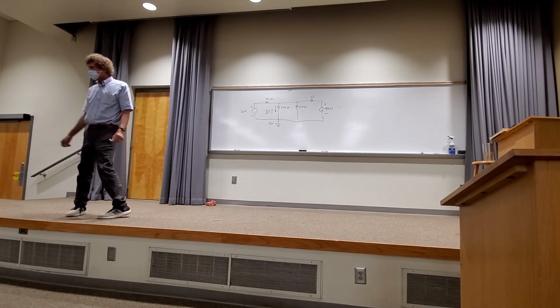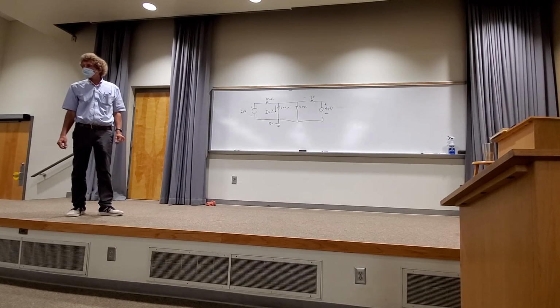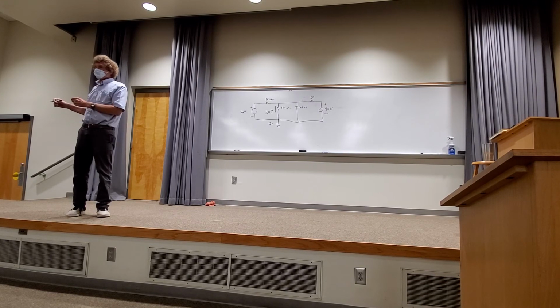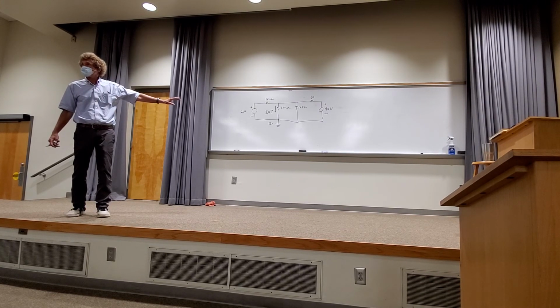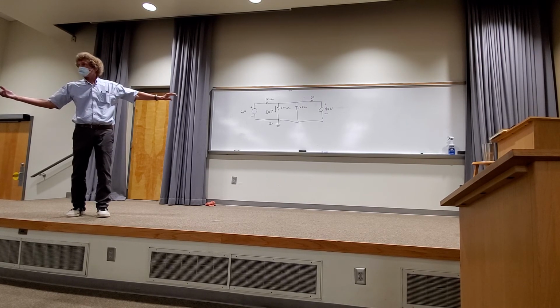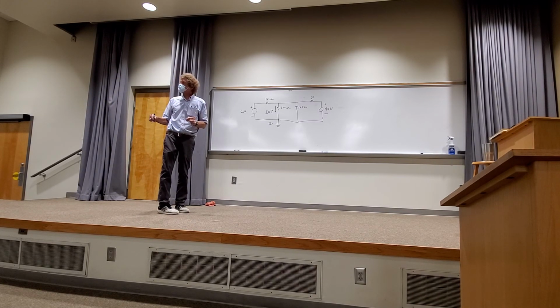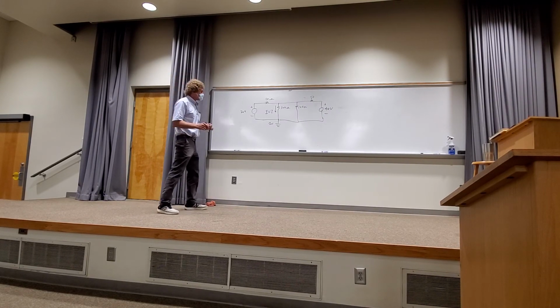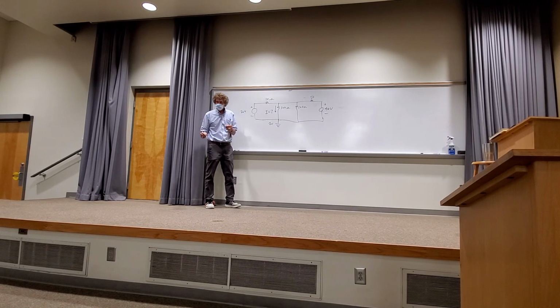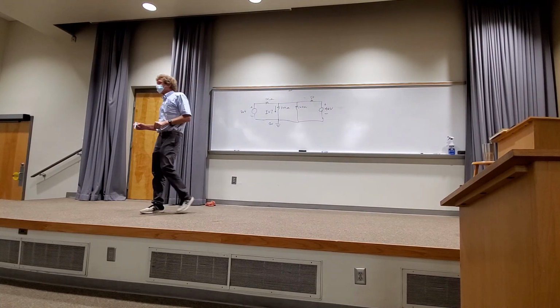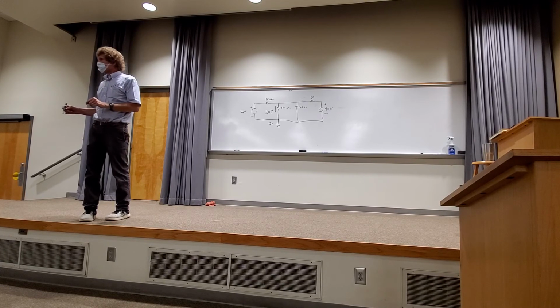Go ahead. So, if there isn't a ground already stated in the circuit, you can put it in. This is the nice thing I didn't tell you: if you need a ground, you can put one in, which is nice. Remember, it's just a reference. If you're troubleshooting, that's the point where you clip your negative lead. Think of it that way, and it'll make more sense, all right? Makes life easy. That's the reason we use a ground. So that's 0 volts. I put that on there first, right? Now, every voltage in the circuit, here, here, here, will be measured with respect to that ground. Make sense? Yes, sir. Okay?